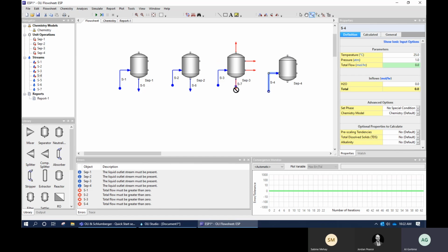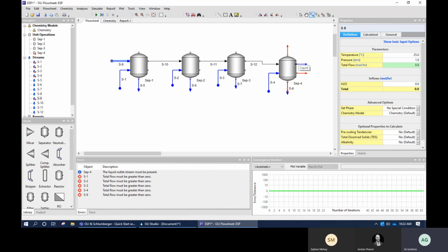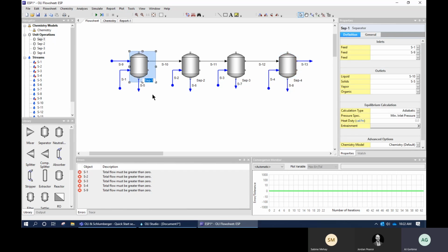This may look odd to you because this isn't necessarily the way you do it, because normally what we would do is what we call a dynamic process, and we're looking at a steady state simulator, but it should still work kind of sort of the way we want it to. So let's just say that this is the sand face, and this is maybe 1 meter in. Let's just say this is radial flow, right? 2 meters in. Yeah, let's make it 1.4 because I got to do it by the r squared, right? And then whatever that is, somewhere about 2 meters, let's say.